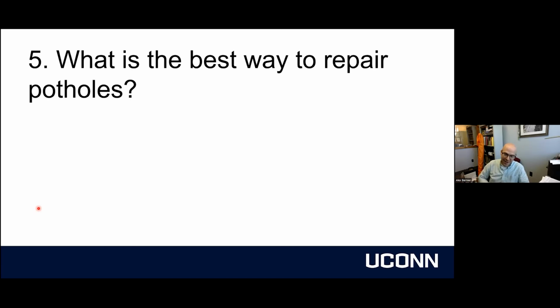One thing, and we've had a lot of conversations with municipalities, is a pothole repair. Any repair is only going to last 3 to 5 years. You can expect it to last that long. If it lasts 7, fine, but you can't expect it to last 8, 10, 12 years patching a pothole. There's a good chance that the material around it is also going to be not great.